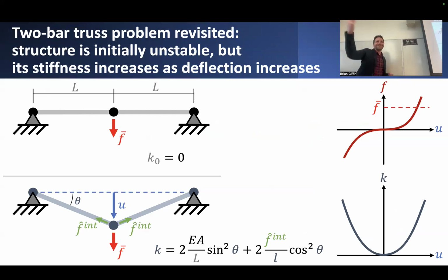And I love this example. This very simple example that we pondered back when we said, let's look at this simple 2-element problem, connected end on end of these 2 truss elements. We tried to analyze it in our MATLAB code and by hand, and we determined that it was inherently unstable when we tried to do this analysis. We couldn't solve it using simple linear structural analysis.